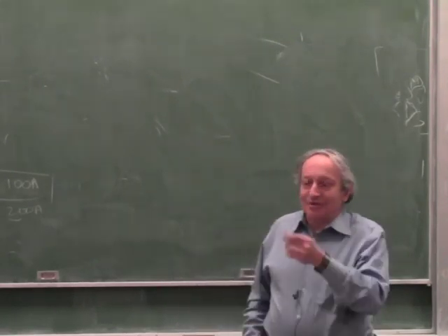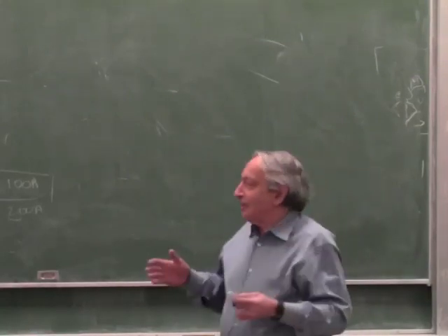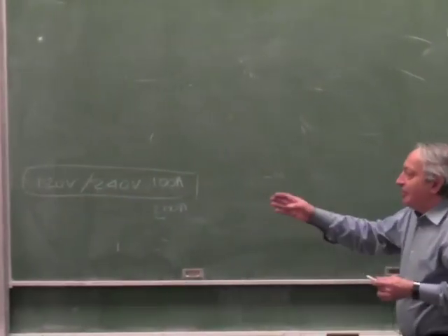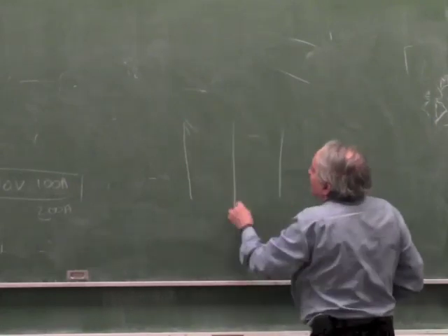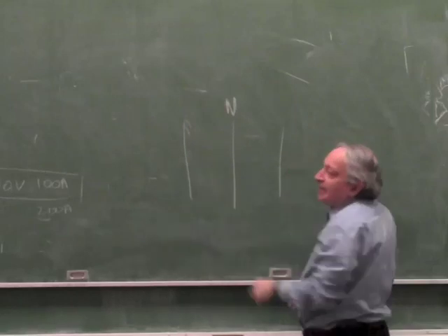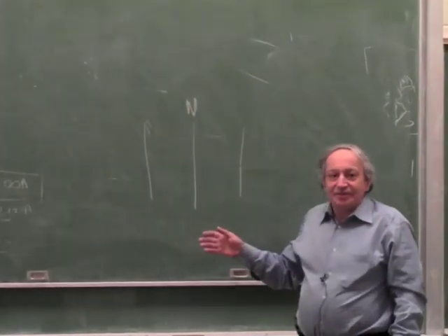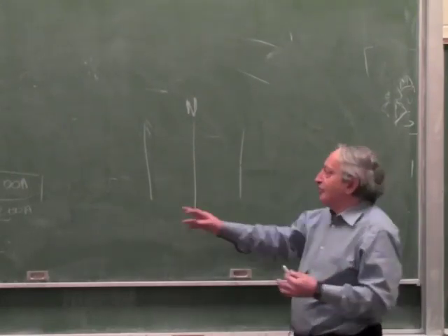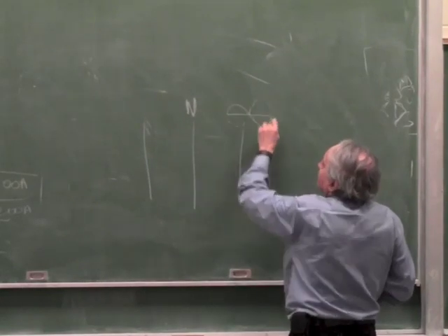Okay, good. So the first surprise is most people don't even understand how the house wiring works. How do you have 120 and 240? The way you have the two voltages, in a house you have a neutral coming in and two phases 180 degrees apart, each one carrying 120. There is actually no 240 coming into a house. There are only two phases of 120.